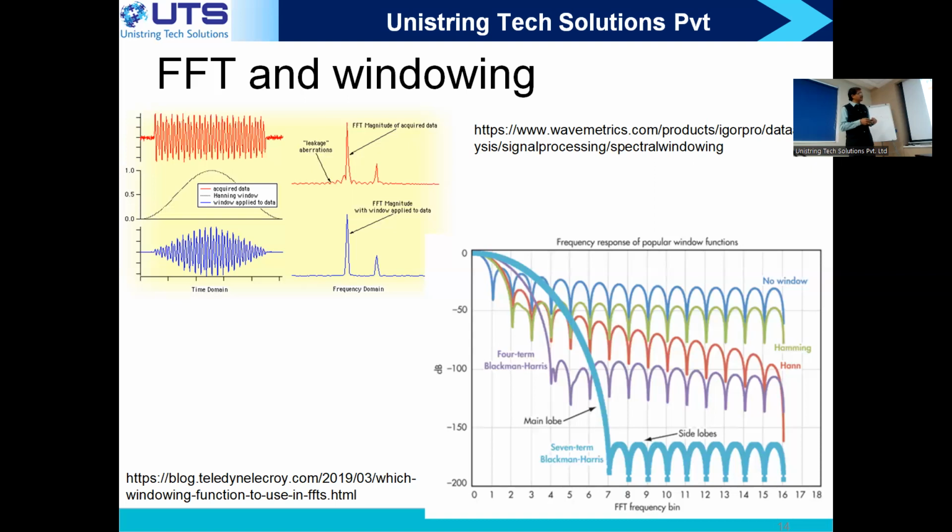So this one, the no window, is good in that at the second bin, bin number 2, I am able to detect, but that will be only 13 dB down with respect to the peak, and it will be slowly fading out. Even if you go 10 bins away, it still has not achieved a 50 dB side lobe. You see this? This is a very important thing.